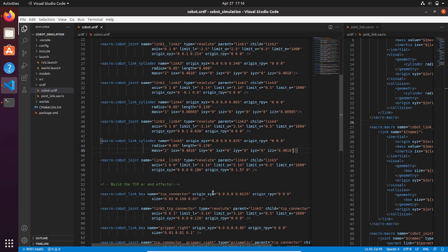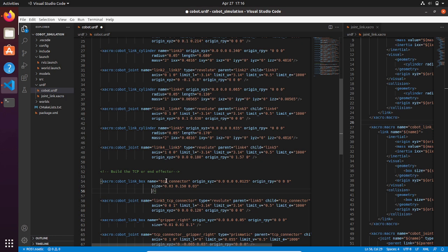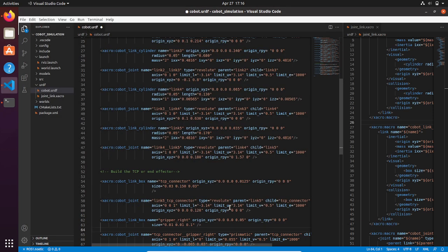So we just need to keep the formula for inertia values that has the center of rotation at the center of the box itself. So it is a matter of putting a numerical value in the variables W, H and D, and you are going to arrive at the value of inertia that I have retrieved. So again, feel free to challenge this number.